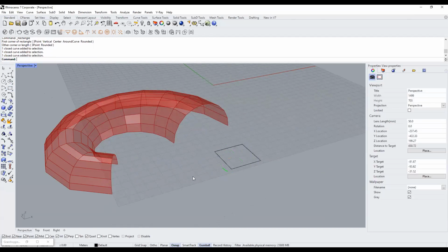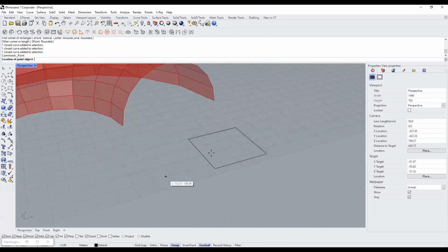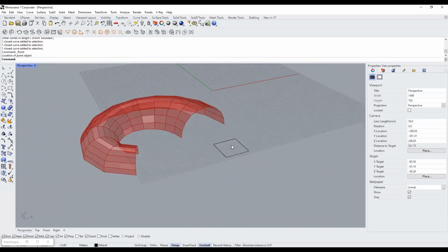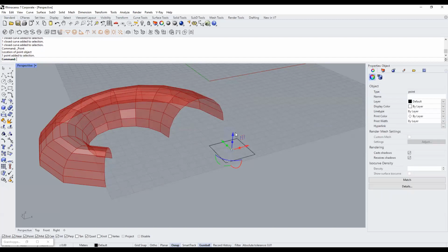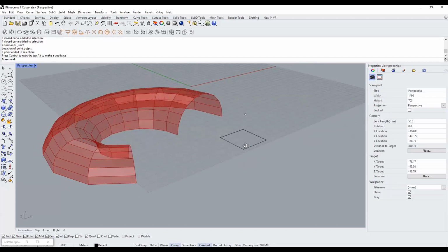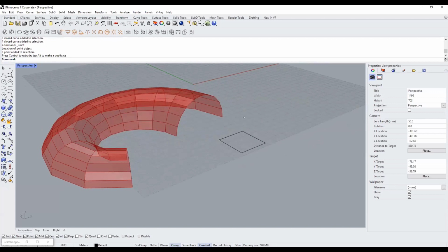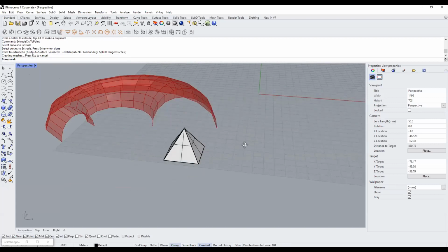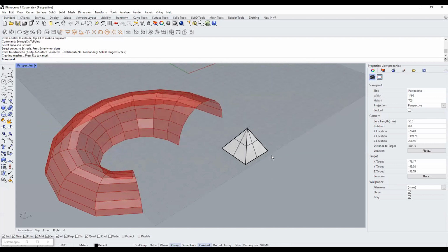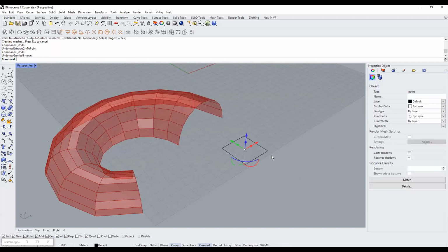So first, you take the panel. To create a prism, you will find the center of the object. Once you find the center of the object, you will move the center point to get the tip of the prism. After you do that, we will use a command called extrude curve to point, that is a component in Grasshopper, and specify the curve and snap at this point to get a prism. That's it. So these are the steps involved in creating the module.